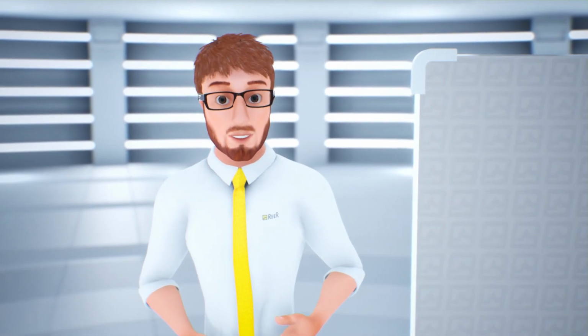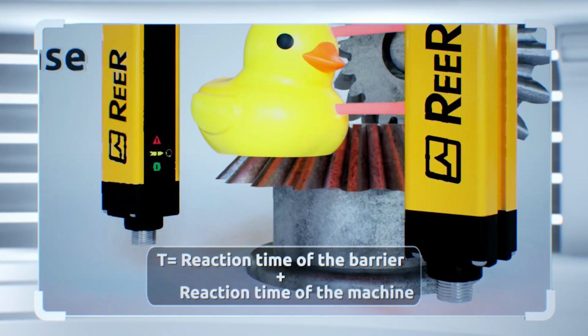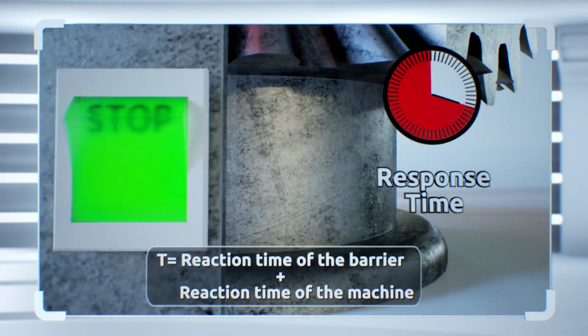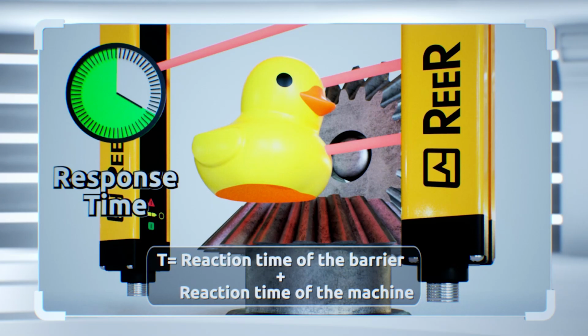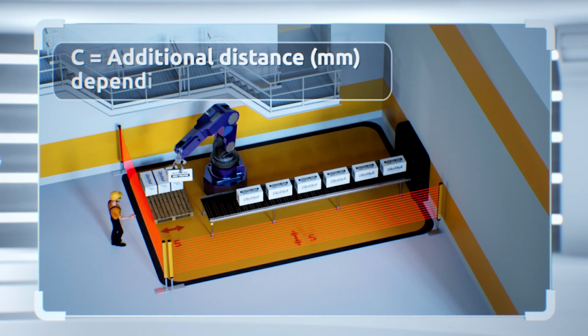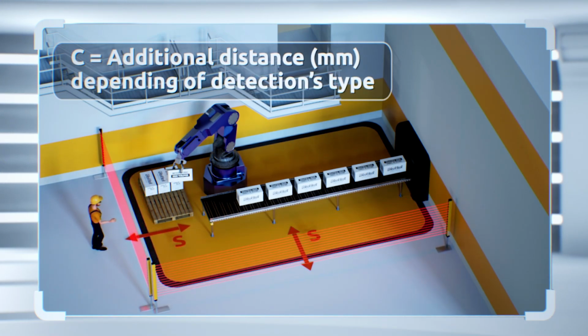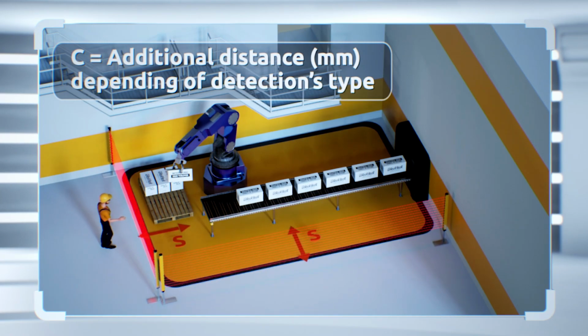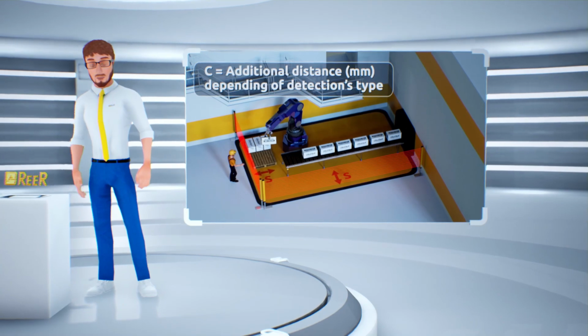Total stopping time of the machine, T coefficient, consisting in the reaction time of the light curtains plus the reaction time of the machine. 3. The additional distance, C coefficient, expressed in millimeters depending on light curtain characteristics like type of detection and type of mounting.